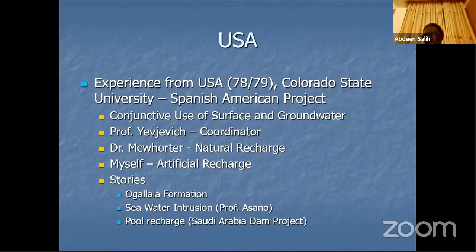They thought of a lot of things. At that time, water harvesting was not as widespread as now, but they thought of water harvesting using playa lakes. They thought of introducing water from a neighboring state, which wasn't very easy at the time. The playa lakes are just like pools that collect rain, but they turned out to be a very bad recharge method because of the sediment which settles down and makes the recharge very poor.